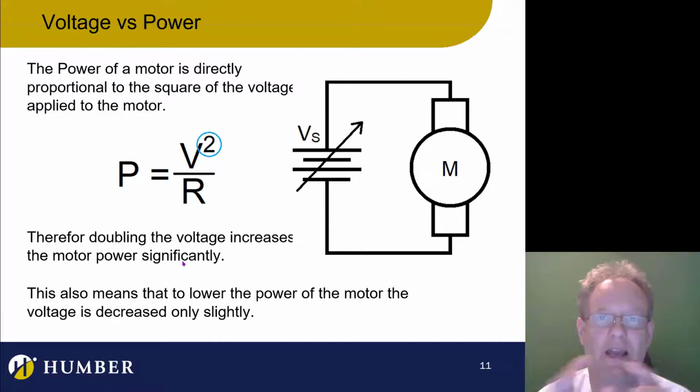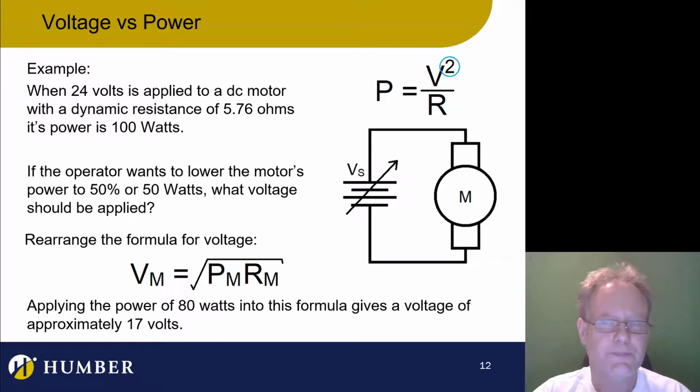Again, if it's a 100 watt motor and it's actually doing 100 watts, mechanically it's transferring 100 joules of energy per second. Stick with the voltage for the motor. Don't increase it. But if the load is lighter, you can increase the voltage, so it's okay. But don't overspeed it. Don't make it go really, really fast, because the bearings will blow out.